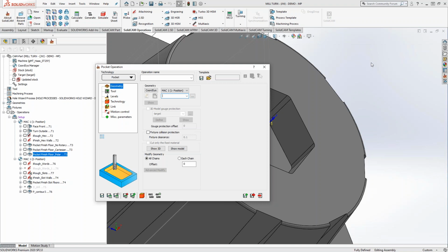So I'm just reading Frank's question again. So the point-to-point makes sense. If I move along the z-axis to select geometry, can I still choose a consistent z level for actual machining? If I understand the question, when you choose the geometry in a 2.5D toolpath, all of that geometry gets projected to your tool plane. So it's basically, it eventually will be a consistent z level.